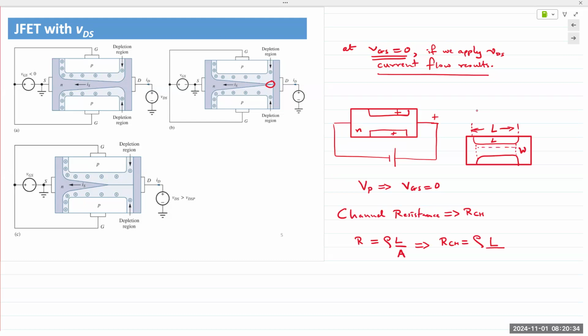And if you imagine a three-dimensional structure, with our implants, we have, let's say, a 500 micron silicon wafer, and the implant would be just a few microns deep, probably not even a few microns. So the depth of the implant into the surface of the silicon wafer gives us the thickness of the channel, and the thickness multiplied by the width gives us the cross-sectional area.